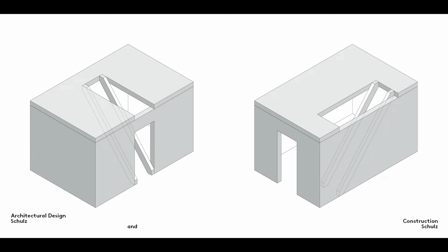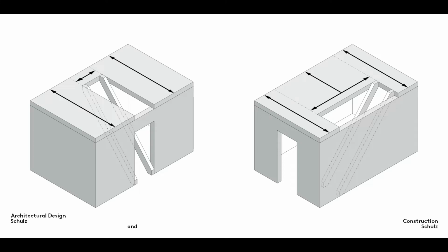If you compare the span direction of the floor and the position of the stairs in these two drawings, you will see that there are two ways of making openings for stairs in a floor: parallel to the span direction or at right angles to it. And though you may not realize it immediately, this choice has a considerable impact in terms of load bearing. Let us take a look at the various forces at work in the floor.